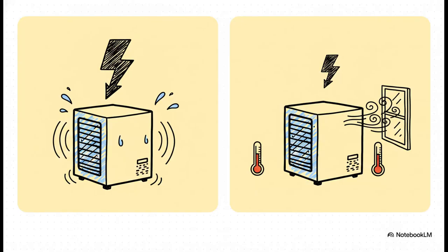Let's see how this builds into a complete paradigm shift. Under the old traditional cooling model, fighting to get water all the way down to 7 degrees meant your compressors were just screaming at high load. They were consuming maximum electrical energy. But under this new AI-era cooling model, targeting 15 to 22 degrees means the compressor load is remarkably low. And even more importantly, it unlocks something the industry calls massive free cooling potential.